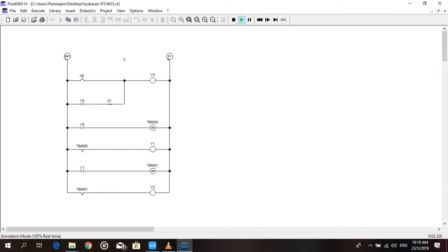After 10 seconds of X0 being pressed, auxiliary motor Y1 will be energized. Timer relay timer 001 is set as switch on delay for 5 seconds, after which Y1 running will start to energize and activate. The stop button X1 will stop the operation and return it to its initial state when it is pressed. This is because X1 acts as the circuit breaker.